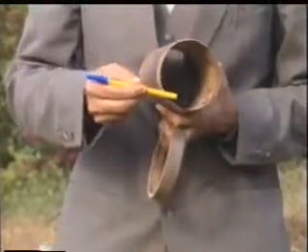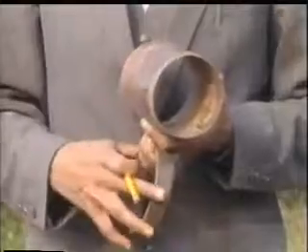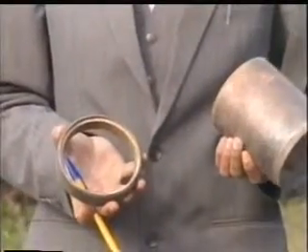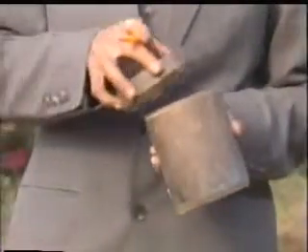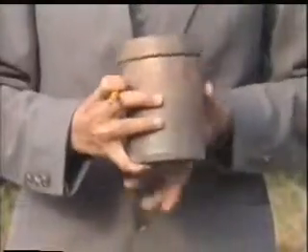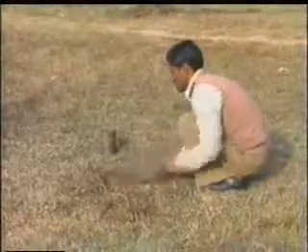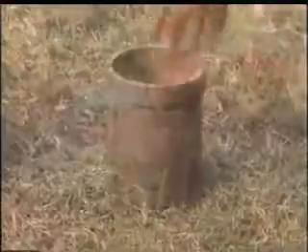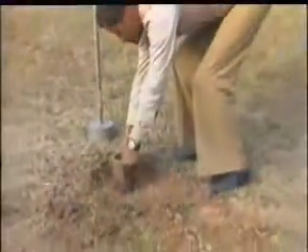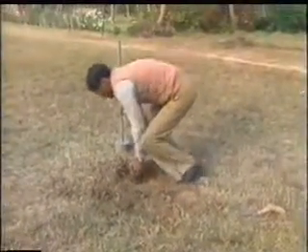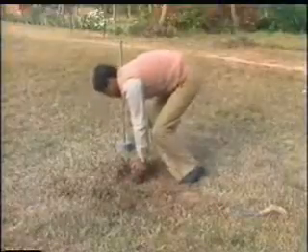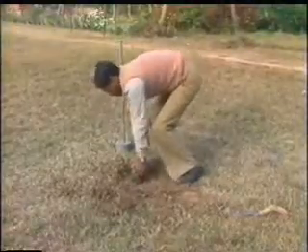Relatively undisturbed samples can be obtained with core cutter. The core cutter with dolly is placed with beveled edge on the cleared surface. The cutter is embedded into soil manually.